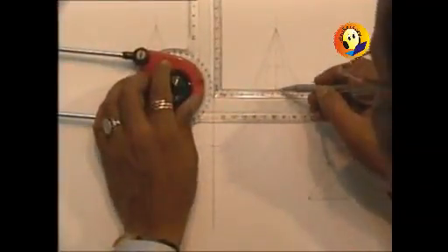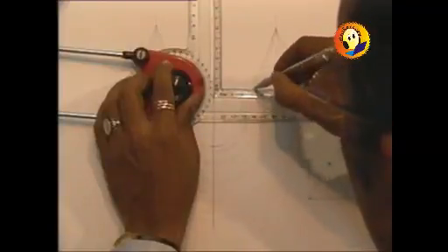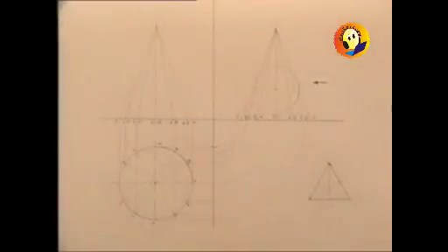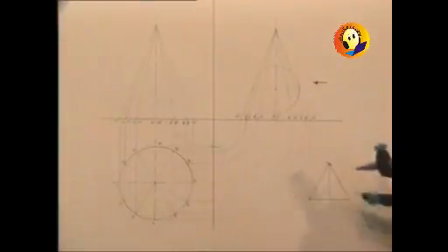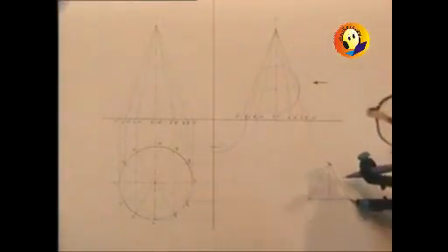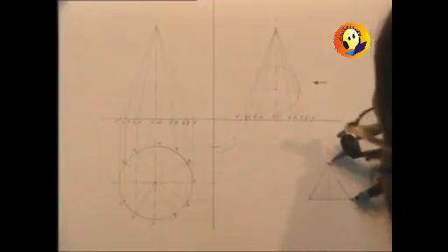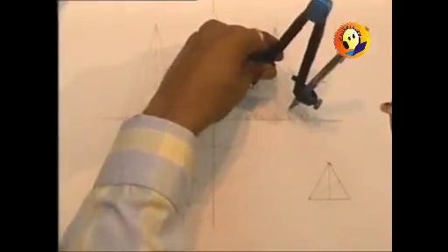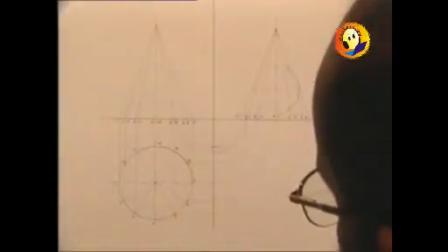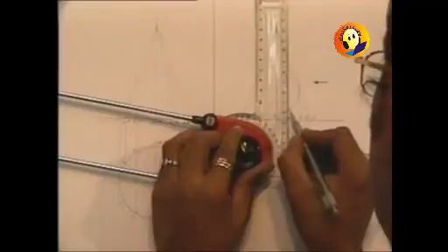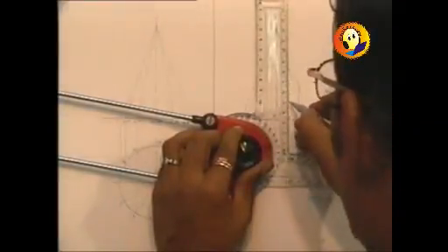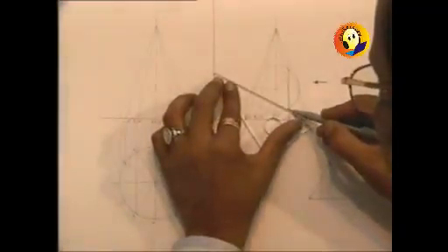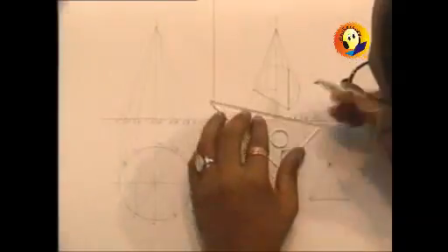So you will be simply drawing a horizontal line to get the vertex of that triangle, and then take the side equal to 40 millimeters and mark the two points which will be forming the triangle. Make sure that they lie on the same vertical line, and they will. So this is how that triangular prism will be seen in the side view.